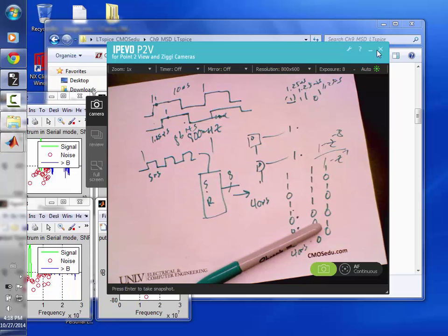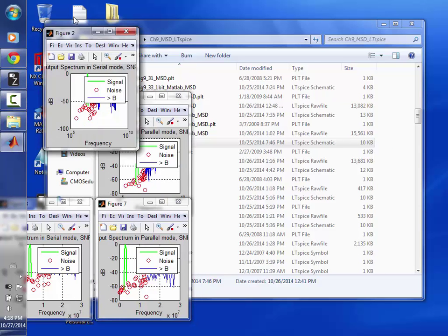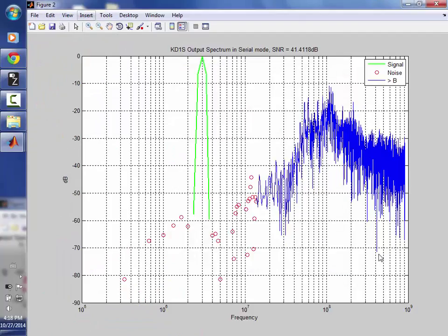Okay, and then again, we're going to go through this. If you look at the spectrums, here I've set my bandwidth based upon the oscillation frequency and the parameter oversampling ratio. So here's my desired tone. When you do an FFT, you get these side lobe points. So there's 2 side lobes, or a total of 5 points here. So you need to subtract those out of your spectrum when you're calculating noise and then limit your bandwidth.